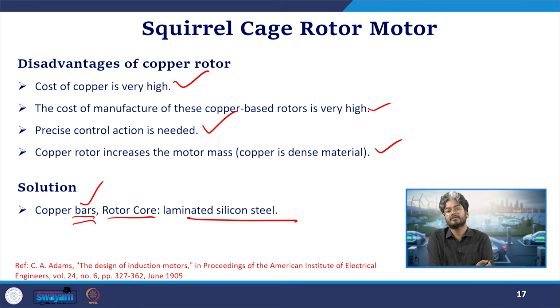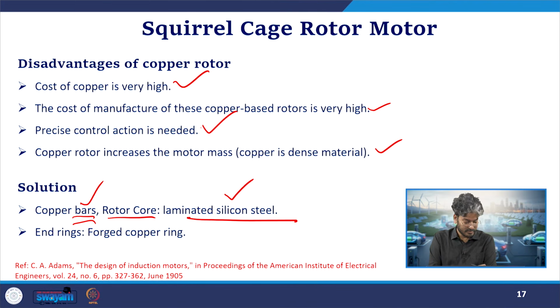So it is limited to the high-end electric vehicles, whereas for our normal or low-end, cost-effective electric vehicles, the rotor will be made of laminated silicon steel material, and the bars present inside will be made of copper, such that our performance is comparatively good, but not as good as the 100% copper-based motor, but we will be saving much on the cost or the initial investment requirement in this case.